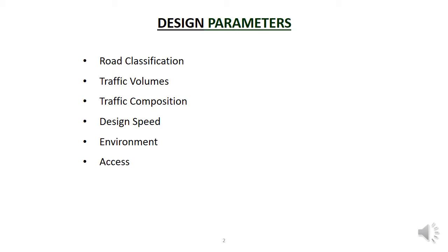Most roads provide access to properties, so traffic from the properties needs to be able to get onto the road safely. The driver entering the road needs to be able to get onto the road and up to speed without getting hit by traffic on the road. And so they need to be able to see enough of the road to judge where there is a suitable gap in the traffic to do that.